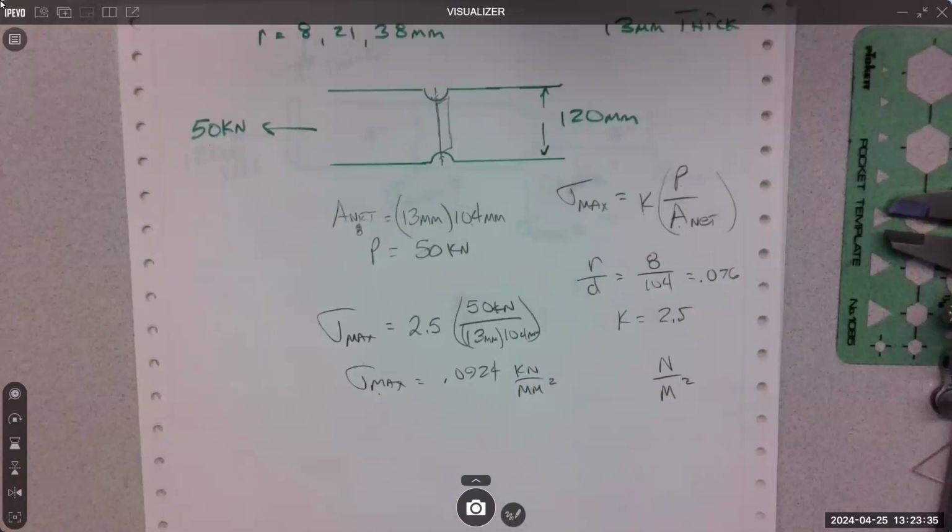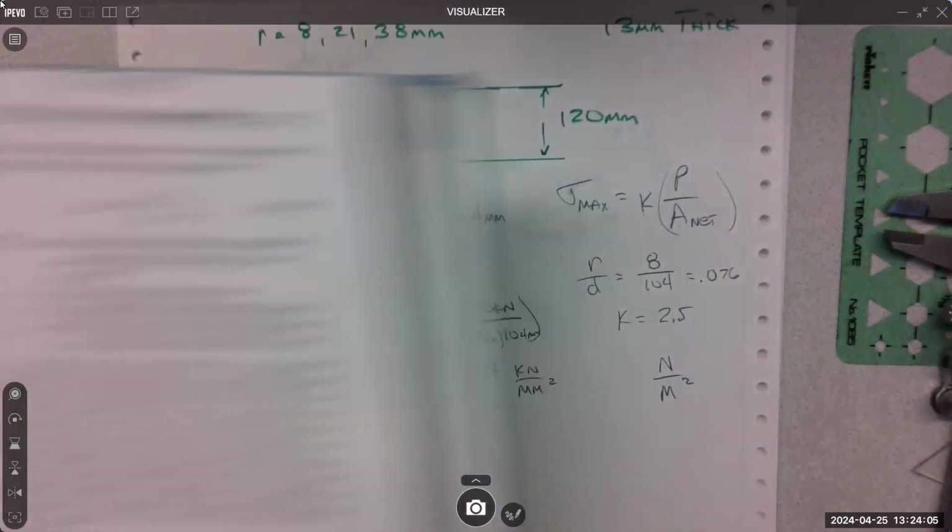Okay, I'm guessing that's going to end up to be a factor of 3. And I'm going to end up with 92.4. But what did the book get? 88.8. Yeah. So I'm off because I used a different K value than the book. I got 0.089. Oh, so you were right on it, and you used what as a K factor? 2.41. Okay. Perfect, 88.76 pascals. Perfect. Got 89.